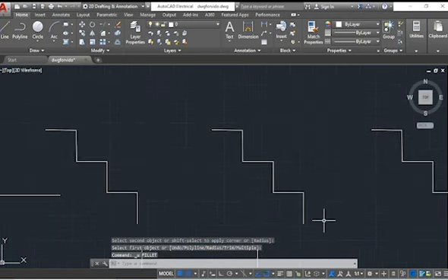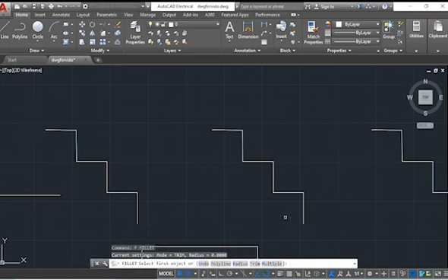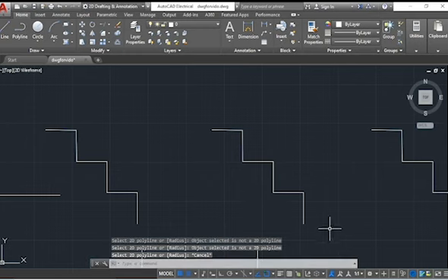Now, I'll show you once again the fillet command. If you want to fillet all the corners at once, then choose the polyline option and specify the radius. Say this time I'll give the radius as 4 and select the 2D polyline. Okay, I think I have undone that.